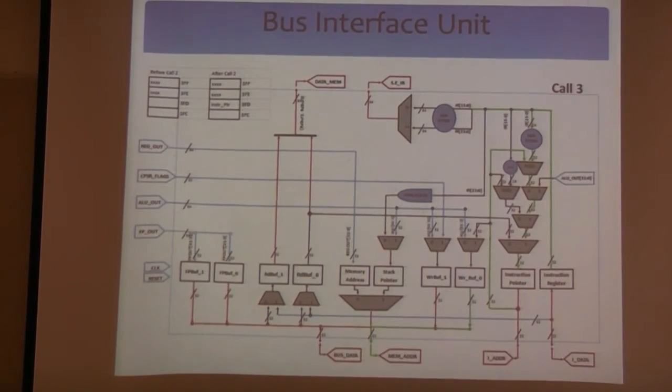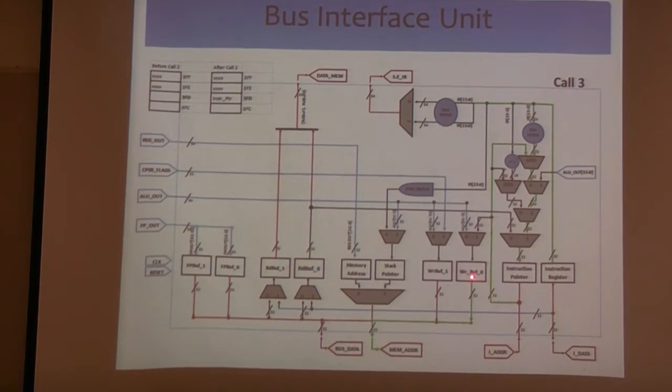And on the third, the value that is in the write bus 0 gets pushed into the memory, and the next instruction is calculated using a series of multiplexers here and re-pushed onto the instruction pointer. So as you can see, here's our stack block, and the instruction pointer value that is being saved onto the stack is stored in the least significant word of the stack block in memory. The higher word is not used, so it is just left with X's.